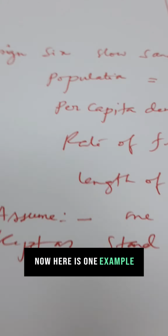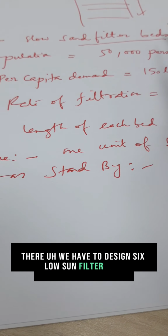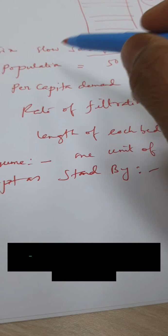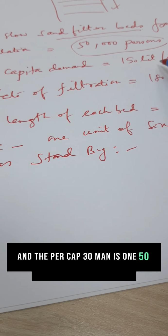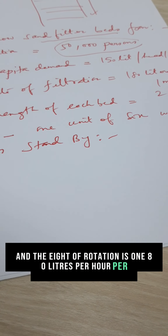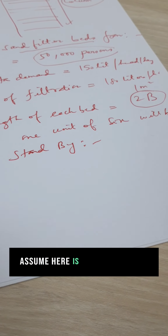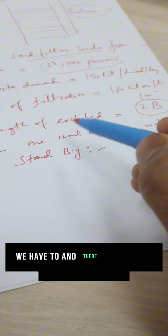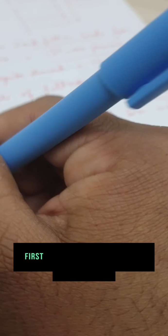Here is one example where we have to design 6 slow sand filter beds from the following data: the population served is 50,000 people, the per capita demand is 150 liters per head per day, the rate of filtration is 180 liters per hour per meter square, and the length of each bed is assumed to be twice the breadth. There is one more assumption, that one unit out of 6 will be kept on standby. First of all, what do we have to do for the given problem?